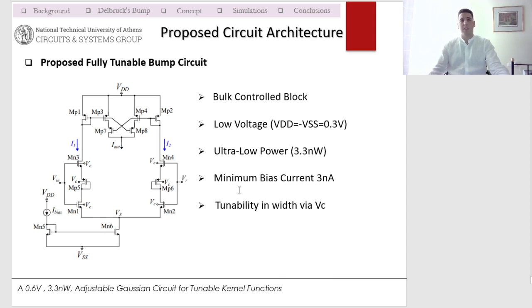In practice, in system-level implementation using such Gaussian function circuits as building blocks, the input and parameter voltages are generated by previous blocks of the system, such as, of course, D2A converters or sensor systems such as analog circuit extraction blocks in active pixel sensors.